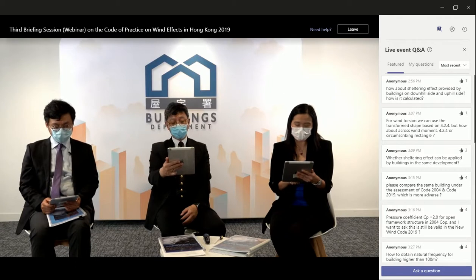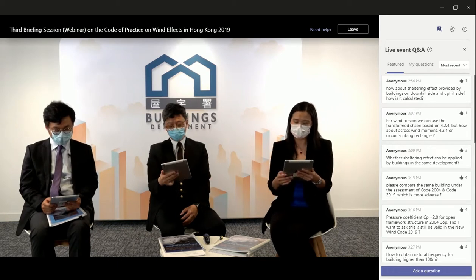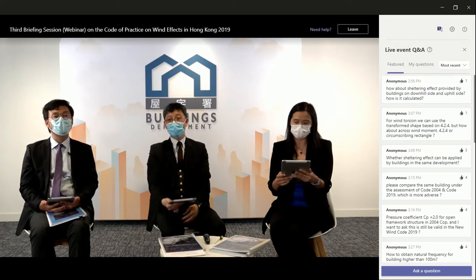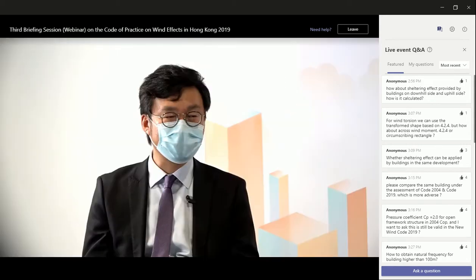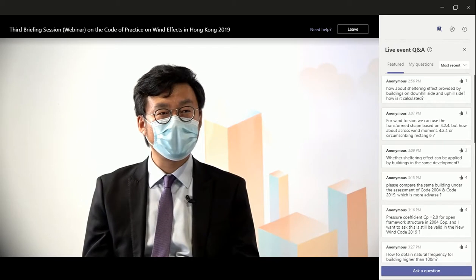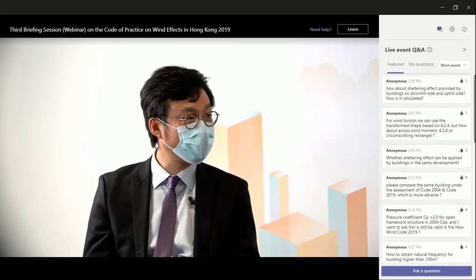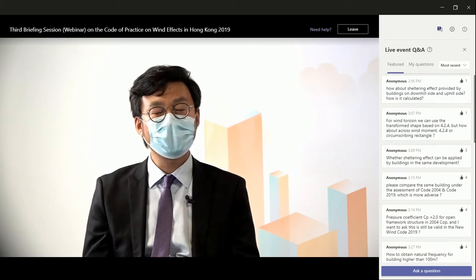So the next question is how to obtain the natural frequency for buildings higher than 100 meters? Okay, Lepton, please. So I think at the beginning of the code, we gave a recommendation on how to calculate the natural frequency. Normally there are two categories. For buildings shorter than 100 meters, we still follow the old rule of thumb, that is 46 over H, for natural frequency calculation.